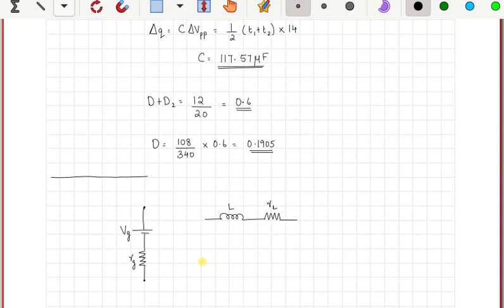Again, if you look at the capacitor, you will find that it comes with a series resistance, and it will also have a series inductance. So this is your capacitor, and this resistance is what is usually called the ESR, or the equivalent series resistance, and this is what is called the ESL. And in these applications, it is mainly the ESR which is going to affect the performance more than the ESL.